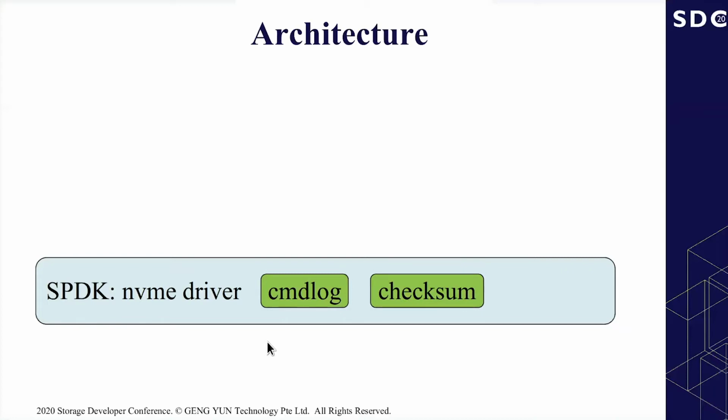Second, checksum. Pynvme calculates the CRC for each LBA when writing data, and traces the CRC value in host memory. At reading time, Pynvme calculates the CRC again and verifies it with the value in memory. It implements an inline, transparent data integrity check mechanism.